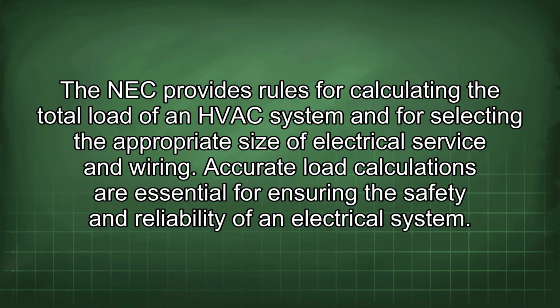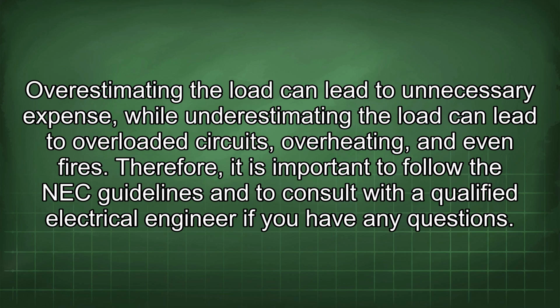Accurate load calculations are essential for ensuring the safety and reliability of an electrical system. Overestimating the load can lead to unnecessary expense, while underestimating the load can lead to overloaded circuits, overheating, and even fires. Therefore, it is important to follow the NEC guidelines and to consult with a qualified electrical engineer if you have any questions.